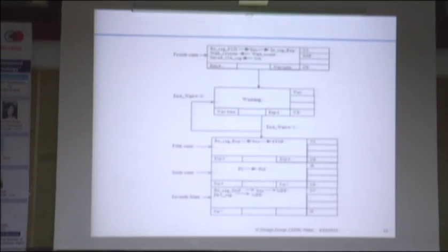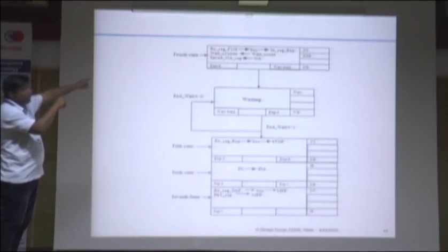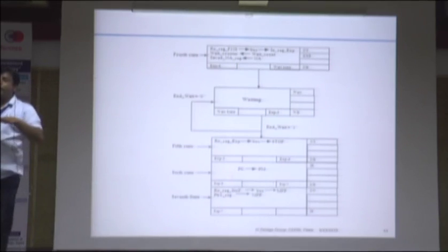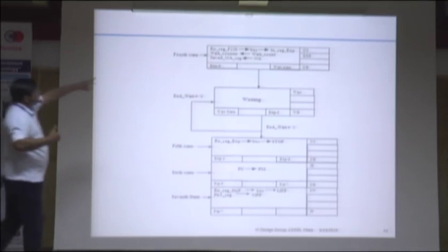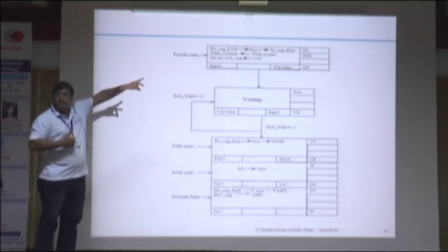Now the result of this F2IS block is available. This register R0, F2IS, will contain the output of this F2IS block. It will be going to the input register of the exponential block, and this exponential block will compute the exponential. So we have to load this data to the input register of this exponential block.